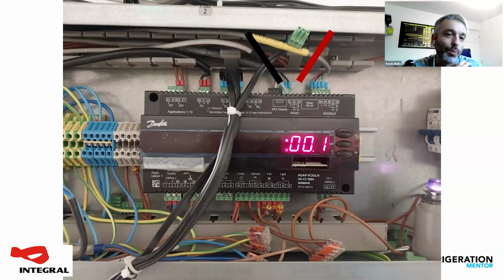Things can drag it down. Water in the plug will drag the 5 volts down. It's only got a very limited amount of current it can put out. It'll protect itself, and the chances are if you take the fault away, it'll recover. You can also take the wires out of the plug or take the plug off the transducer. If your 5 volts comes back, the fault is at the transducer end, not at the controller end. It's quite rare to kill the output from the controller. It's much more common that something drags it down in the field.